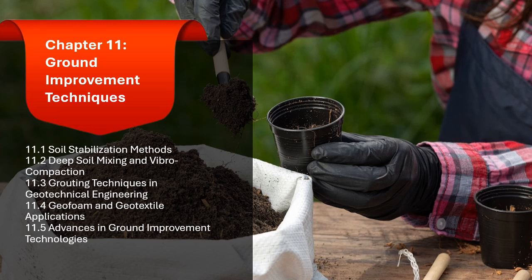11.2.2.3 Advantages of vibrocompaction. Increased density and strength. Vibrocompaction significantly increases the density of loose granular soils, thereby improving their strength and stability. Reduce settlement. The technique helps to reduce both immediate and long-term settlement of structures by densifying the soil, making it more resistant to deformation under load.